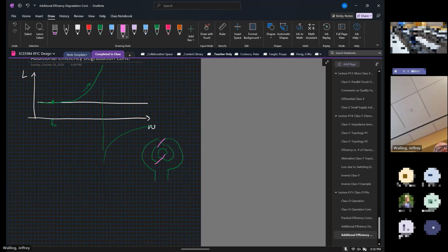So the pink is a crossover where, as I add more vias to this thing, I'm going to a lower metal. The lower metal is lossier. I'm getting closer to the substrate. I might be reinforcing eddy currents that are flowing in the substrate, so I'm getting more loss from the substrate. And I have more crossover points, so I have more capacitance. All of these things are counteracting, and that's really why the quality factor you find is best for a single loop that doesn't cross over.